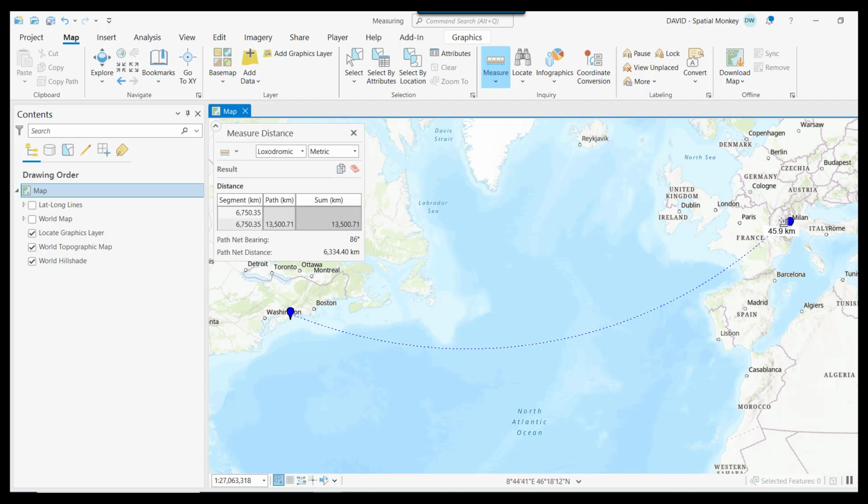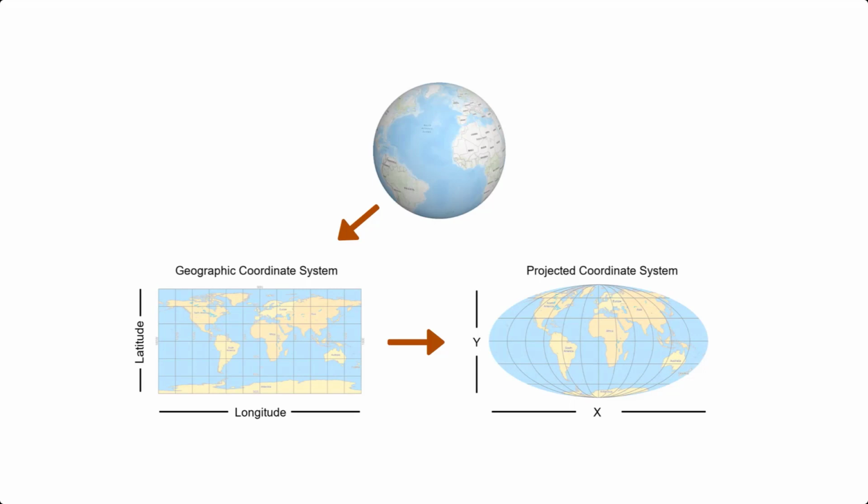The final option in the measuring tool is a great ellipse. A great ellipse distance is very similar to a great circle distance. It is sometimes used in navigation and will produce a very similar distance to a geodesic distance. However, for most users, the geodesic setting, the shortest path between 2 points, is likely the option that will be appropriate for most users. The complexity in measuring on maps is all the consequence of representing our three-dimensional Earth on a two-dimensional map.